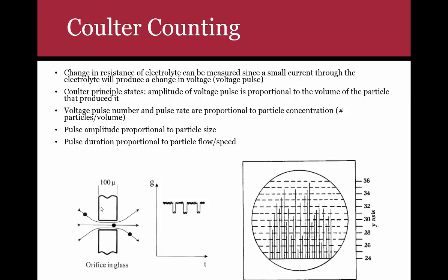than if you were to have a smaller particle. The other thing too is you can also figure out how long it takes this particle to get through this small distance as ionic current flows through here. And that can be seen by this picture again, in that if you measure the time that you dipped in conductance to the time you go back to the original conductance, that amount of time is related to how fast this particle is moving through that space. So you can actually get a lot of information from just this one change in conductance in time.